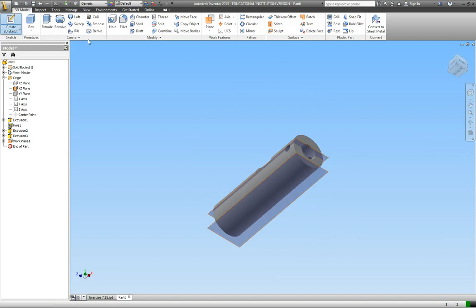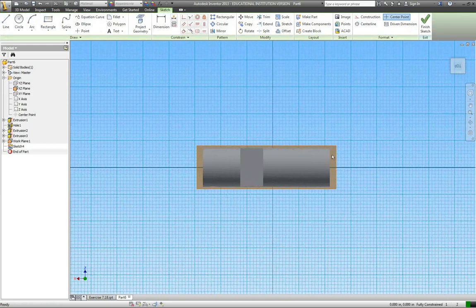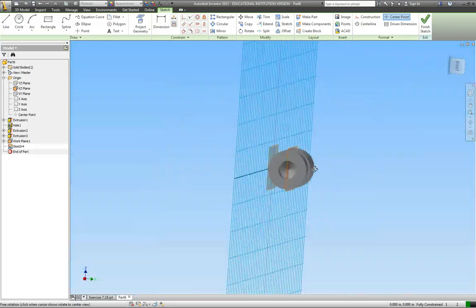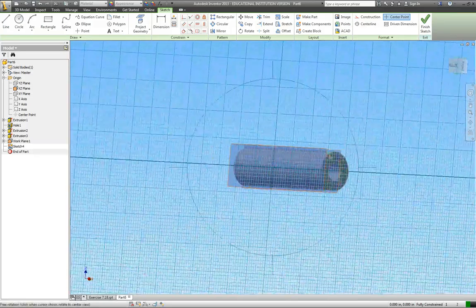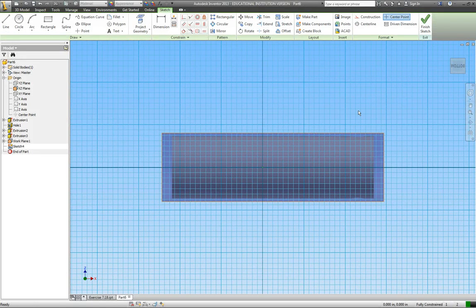So create sketch. Pay attention to your orientation here, how the part changes when we click on it. It flipped around to the other side, so we want to sketch on the bottom. Yours may not have done the same thing, but we want to sketch below the object. So turn yours around so you're looking at the bottom. Now they give us a partial bottom view in the book, and we're going to cut that part out into the object. And so we need to locate it and